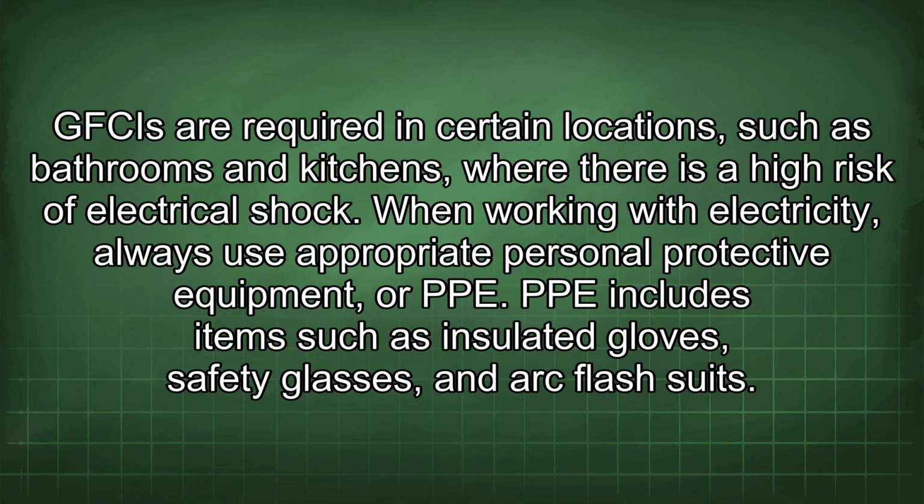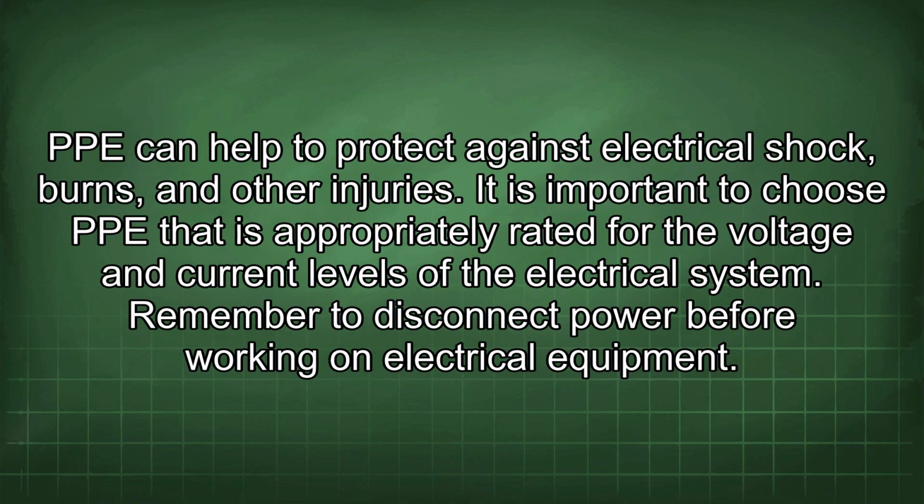When working with electricity, always use appropriate personal protective equipment, or PPE. PPE includes items such as insulated gloves, safety glasses, and arc flash suits. PPE can help to protect against electrical shock, burns, and other injuries. It is important to choose PPE that is appropriately rated for the voltage and current levels of the electrical system.